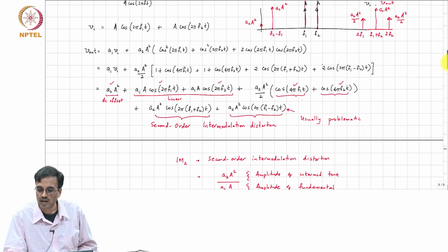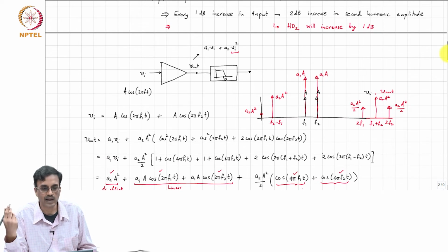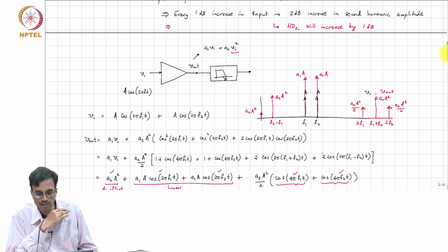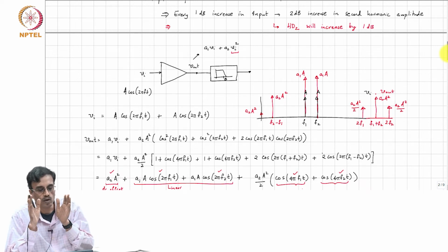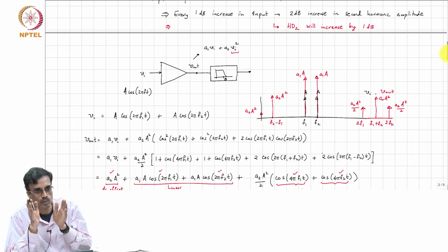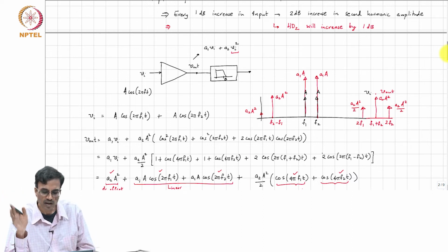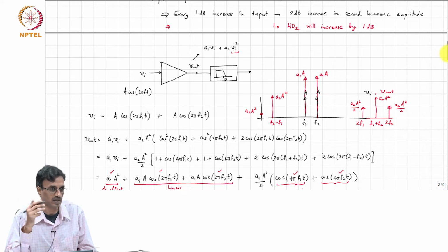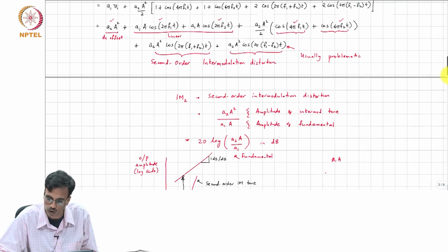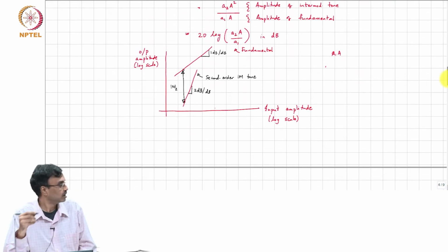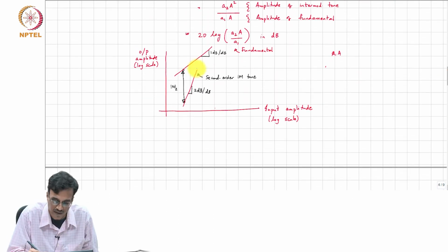But at such large amplitudes, it will typically happen that the amplifier, which is weakly nonlinear only over a certain range of input amplitude, has now been pushed into a strongly nonlinear region, in which case none of these approximations work. So, in a practical amplifier, you shouldn't expect that this curve keeps going up and up.